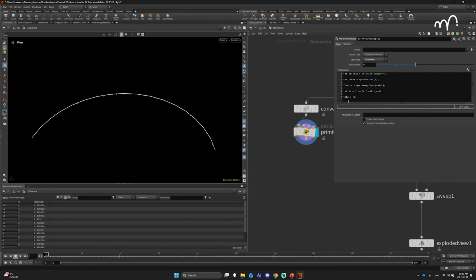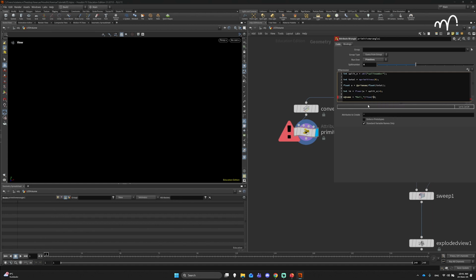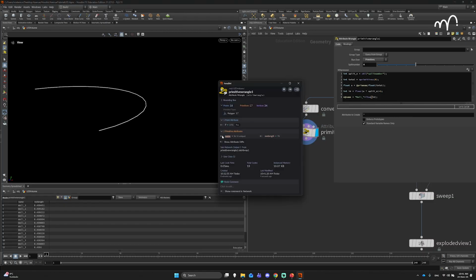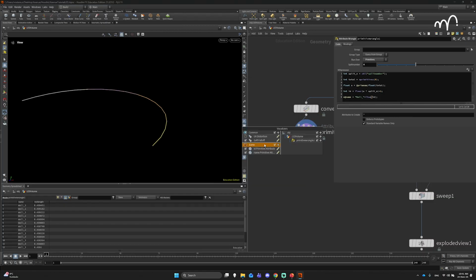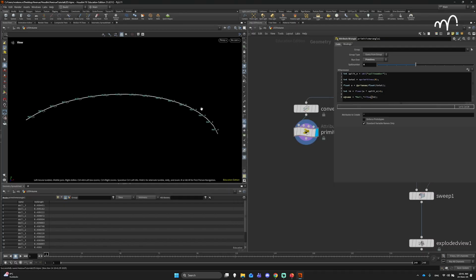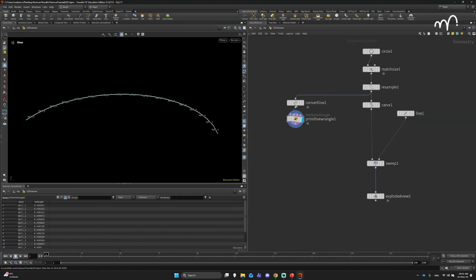Maybe instead of saving it into an integer, let's just do this into a string. So this is going to be string ID or name. I think if we save it in a name, it's better because we want to later split our mesh based on the naming itself, so we can package it and send it to Unreal. So it's going to be wall underscore, and then we're going to add our ID to it. And this needs to be transformed into a string like that. So now we should be able to visualize our names. These are random colors, but if we now do it with labels, yeah, there you go. So every primitive has now its own name, and we can now add some logic based on this splitting.